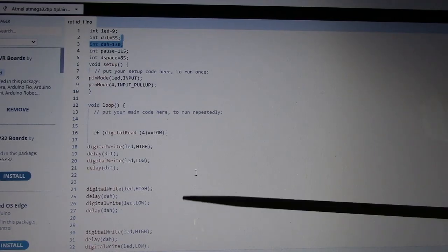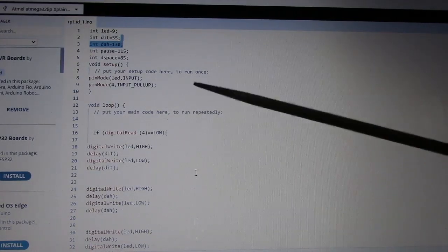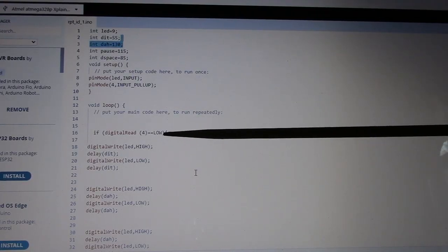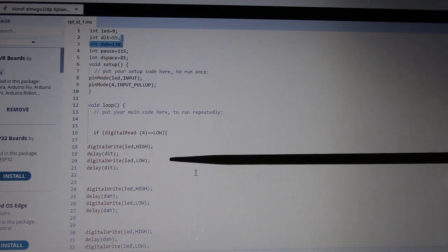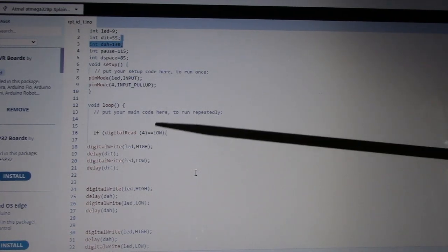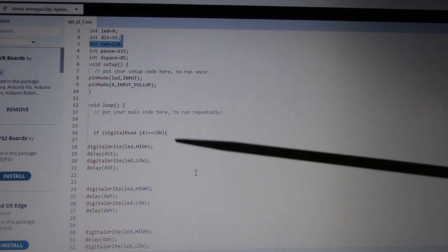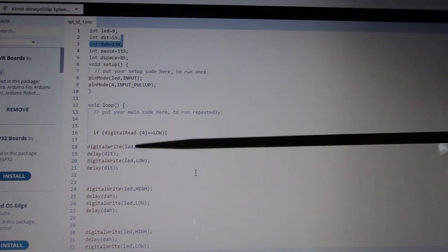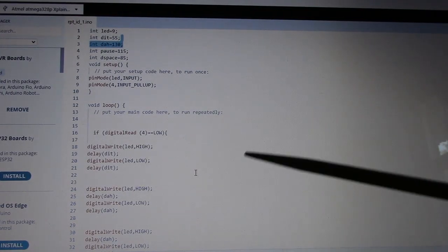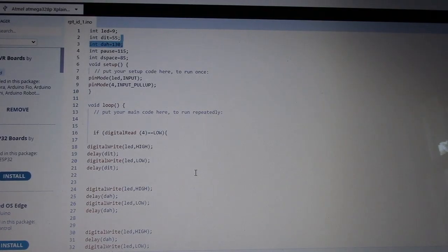So in the circuit I built, when you initially key the transmitter, pin 4 is taken low initially. It'll go through a round of one identifier, one code identifier, and then it stops. And then after this, pin 4 will go high again. After 10 minutes, that will be brought low again, and it will go through the code again and send the Morse identifier, and it'll just keep doing that over and over.